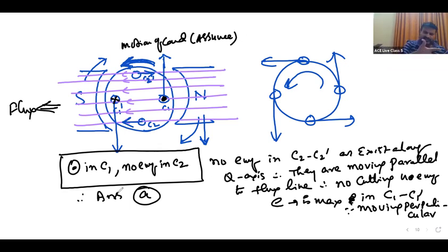Of course, this much discussion is not required. Directly, I am giving it very clearly. After some time I am not going to write anything. Directly you can keep your fingers in. I know the flux direction. So poles move clockwise, the conductor is counterclockwise. You have to assume counterclockwise. They are stationary. Counterclockwise means C1 moves upwards. So flux, current is outwards. Okay.